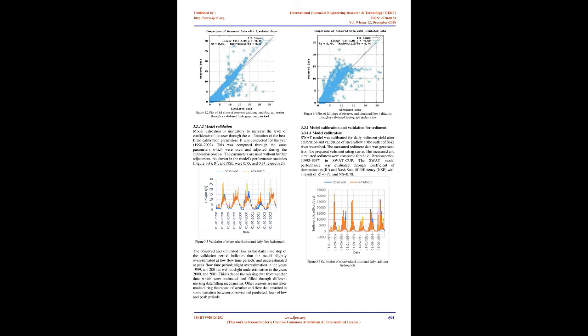3.2.1.1 Model Calibration. The overall performance of the model for calibration has been evaluated with the coefficient of determination, R2, and the Nash-Sutcliffe efficiency, NS. It resulted in 0.82 and 0.80 values respectively. Figure 3.1 below shows the result of measured and simulated values of SWAT_CUP calibration.